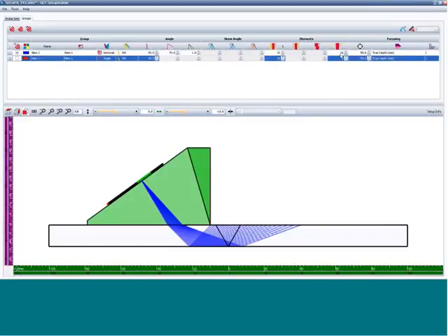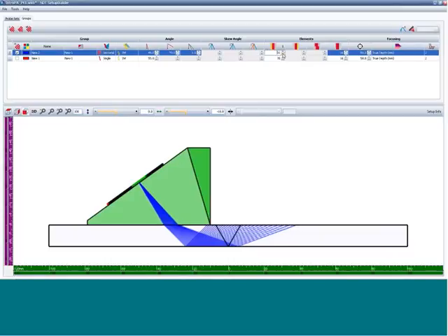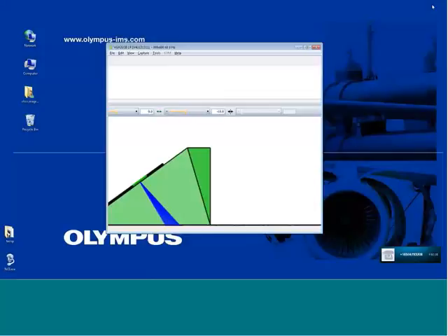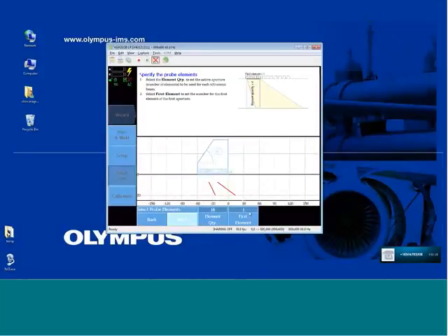16 element aperture, or simulating a 10 millimeter conventional probe starting on element 32. So select probe first element and element quantity.